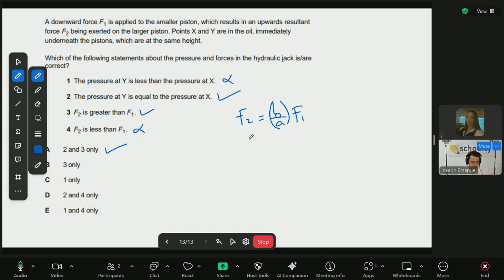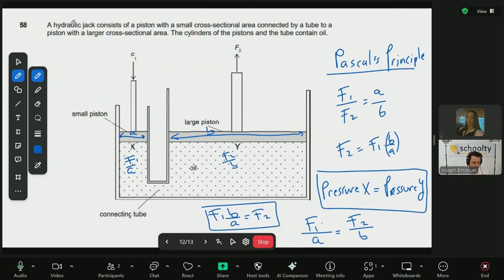So this is a system how hydraulic jacks are actually built. You push on a small area of oil and then it will be leveraged because the area here is bigger. So the force will be bigger because the force divided by area should stay constant by Pascal's law, and this is the tube between the two. So you can hold a very heavy weight and push here with less newtons, less force.